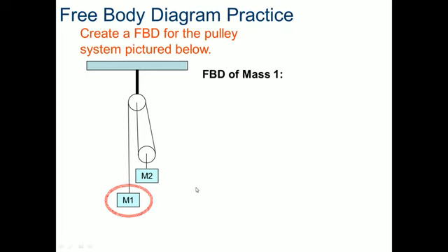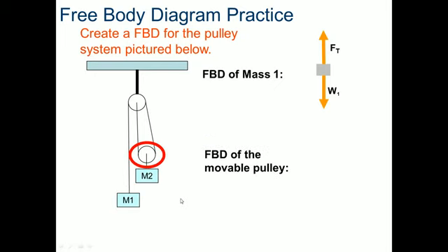To create a free body diagram of the pulley, let's look at the first portion. This has got two different pulleys in it, so we'll look at both individually. I have the weight, I have a tension force. When we're talking about pulleys, we're going to talk about tension forces. When we're talking about cables, we will talk about tension forces.